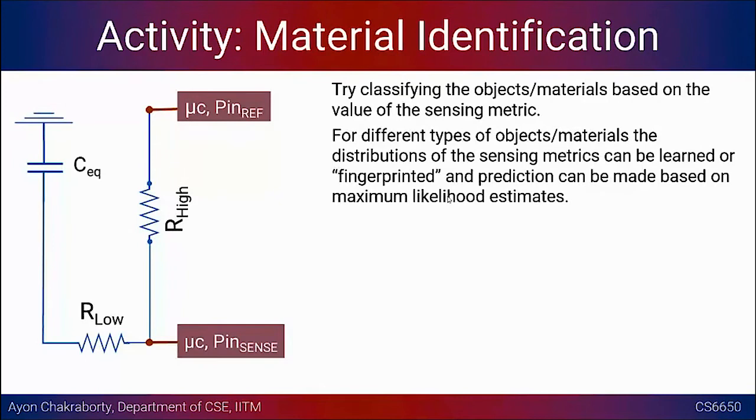What you can do, the other thing you can do, as I was telling you, is that the capacitance is also a function of the object or the material that is touching the system or the sensing pin. You could be touching the pin through some kind of an object, maybe holding something in your hand and using that object to touch the pin. We can convert all these things into very useful practical applications.